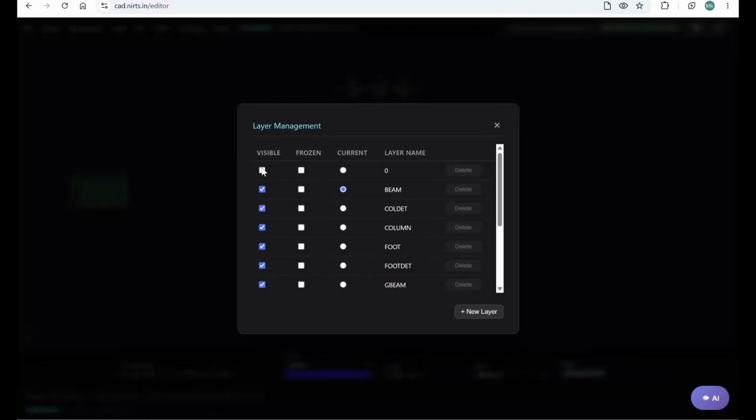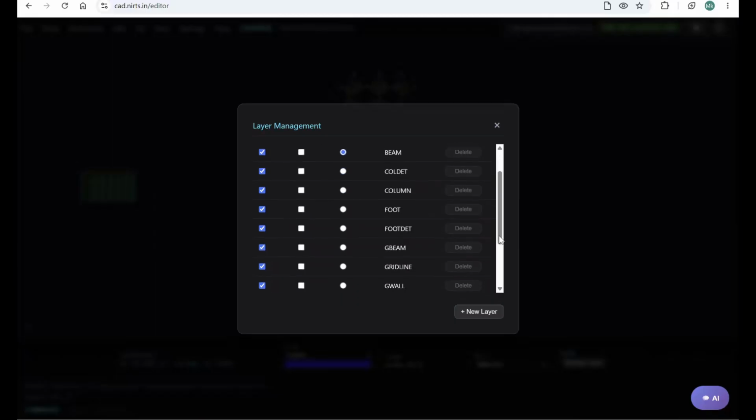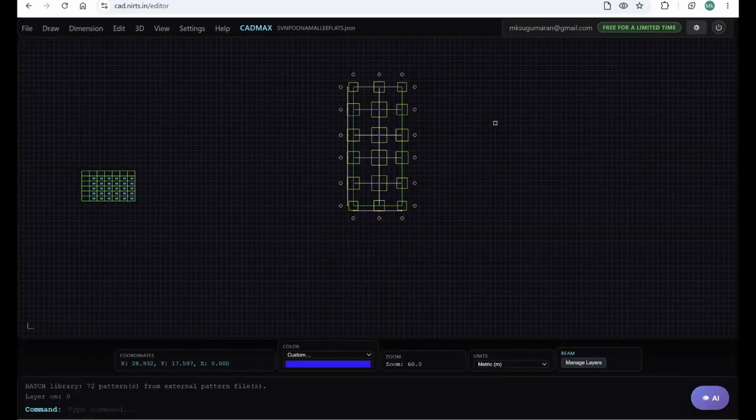So quantities taken out will clearly indicate the steel requirement for beams at elevation of 2.0 m or 5.6 m. Column segments from 0 to 2 m, then 2 to 5.6 m, like that. So it is easy to understand from the CSV file output that you can open in any spreadsheet.